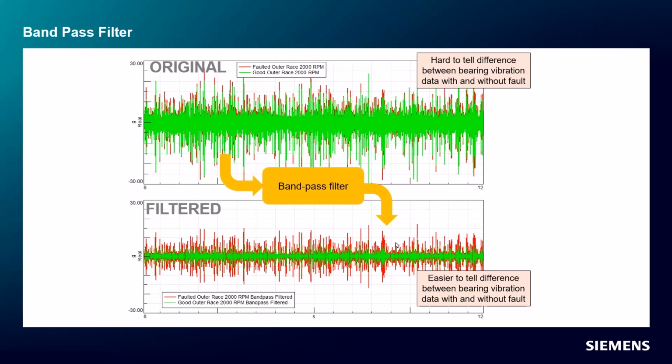And again, we're doing something kind of weird. We're taking advantage of a very high frequency that's out of the range of a normal accelerometer. The reason it's quote unquote out of the range is because there's a resonance in the accelerometer at higher frequencies, and we want to take advantage of that to be able to measure the difference between the good and the bad bearing, to measure this very faint impact vibration that's happening in all this data. It's mind-bending for people that are used to using accelerometers in the normal frequency range.